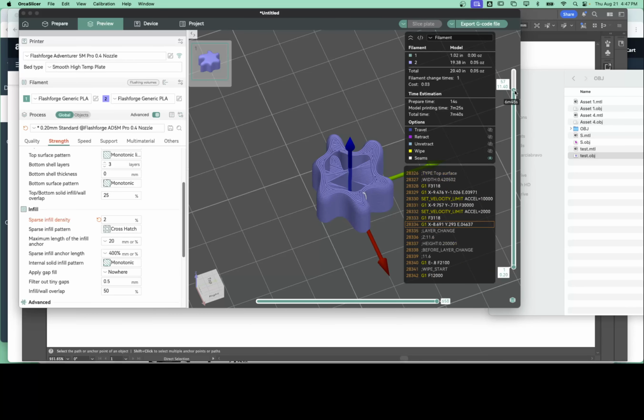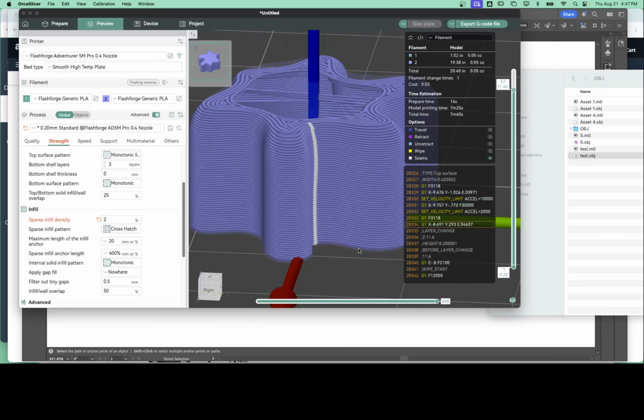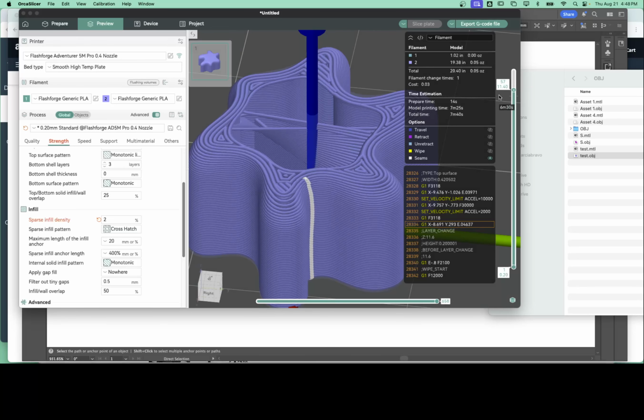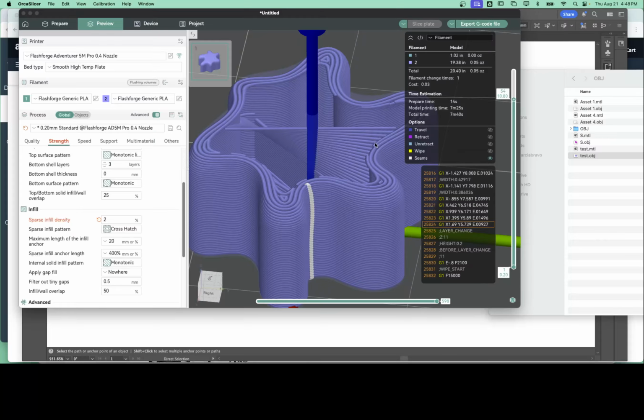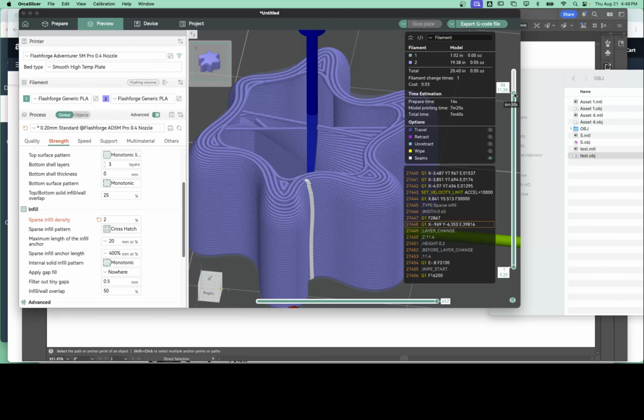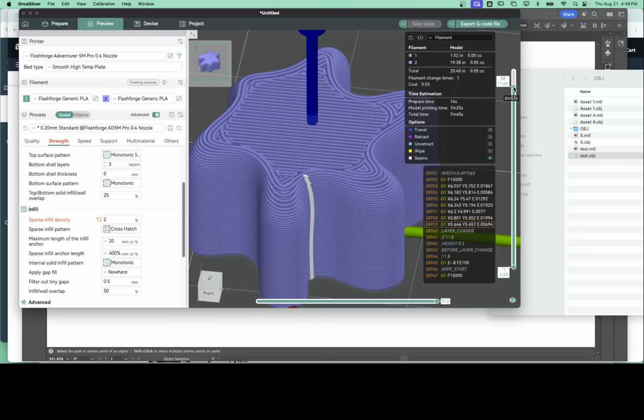Now here you're gonna have some problems because you have no support material for the next layer. So I already know that this is gonna be a fail print, because from this layer, when it starts closing in, there's one step where it might work, but I might not have enough support for this new layer, not enough infill.